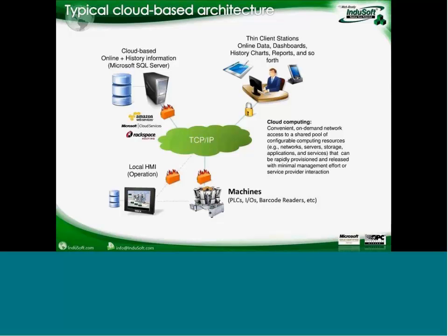InduSoft Web Studio filters the data, consolidates the data, and then pushes the data to the central server, which consolidates information from different machines, lines, or even plants, and saves this data into a central database, and then becomes a portal for remote thin clients that can access reports, online data, and history data from this server using any of the thin clients supported by InduSoft Web Studio.